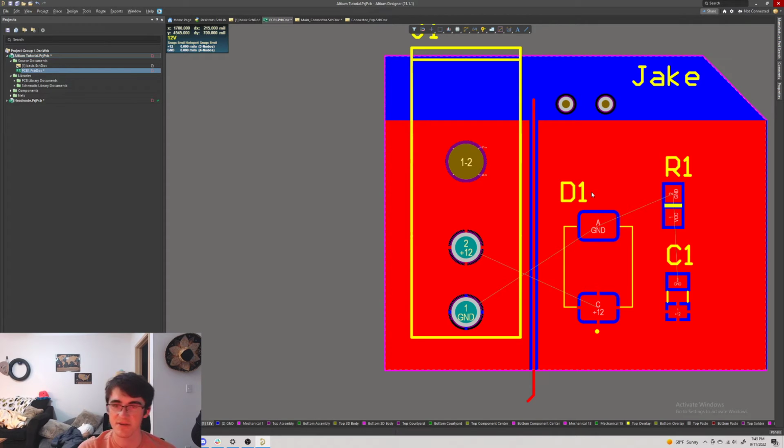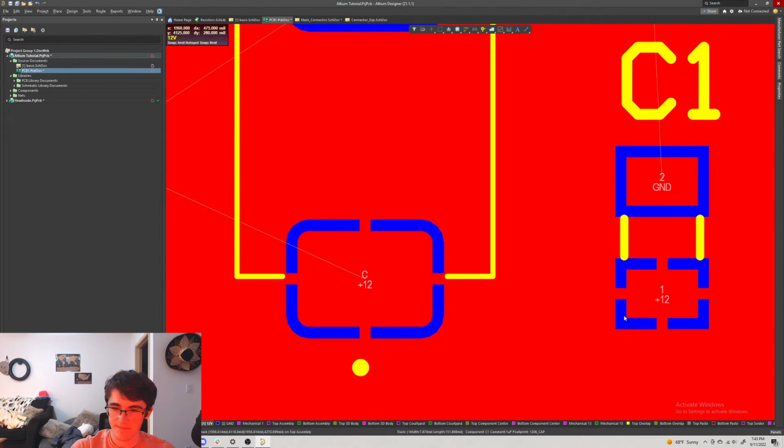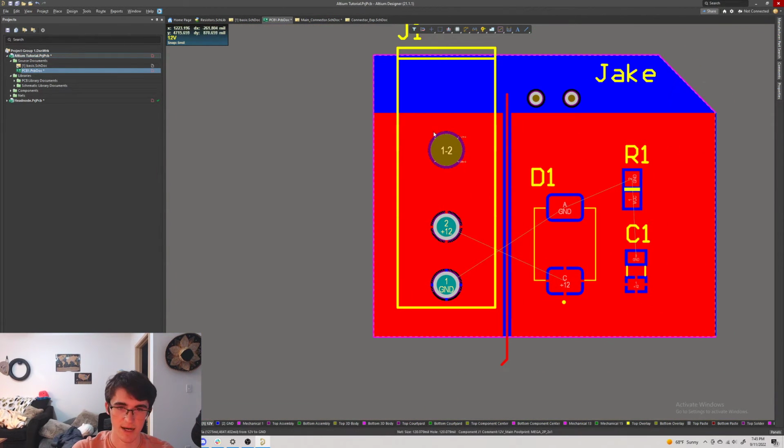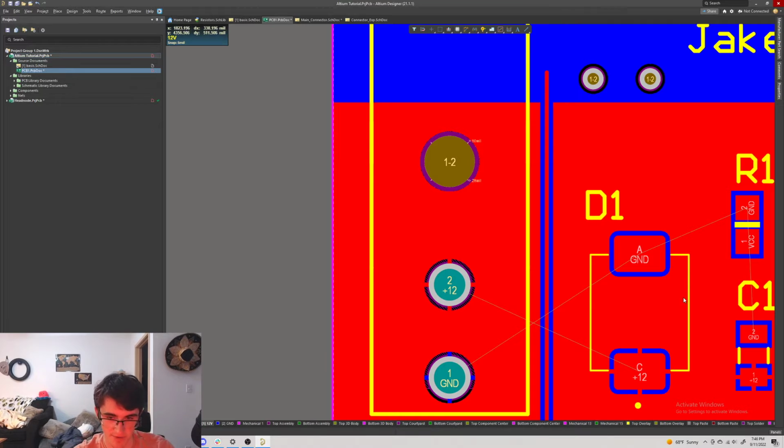These suck, and you can use vias to get around them, but you want to use good design practices to make your traces short so that they don't completely cut this off. Because you could say, oh, looking at this, these two pieces have 12 volts, but they aren't actually connected to the part that's getting 12 volts from outside the board. Altium's kind of smart with this.